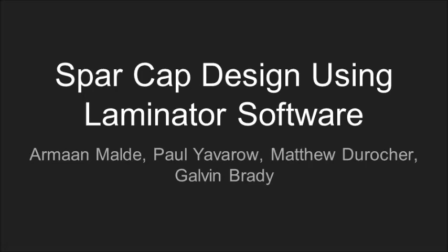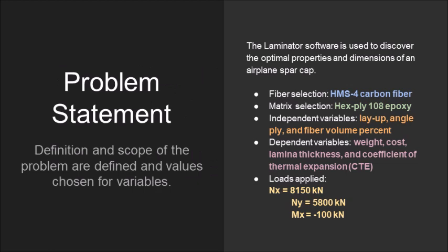In this project, the laminator software was used to optimize the properties and dimensions of a composite material to be used in an airplane spar cap. The design specified that epoxy and high modulus carbon fibers must be used. We hence selected HMS4 carbon fiber and Hexply 108 epoxy, and found the corresponding mechanical and thermal data for these